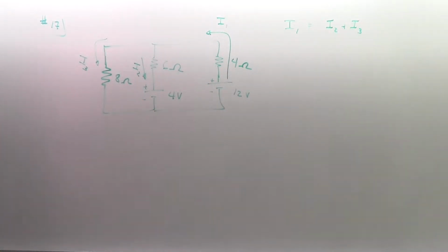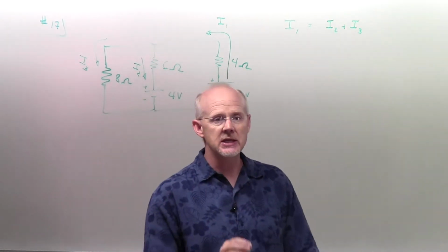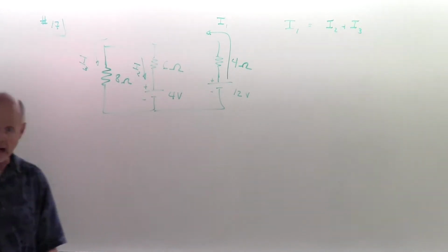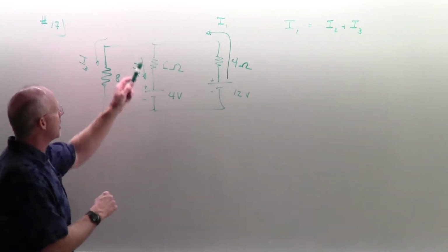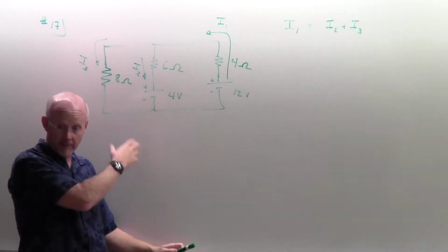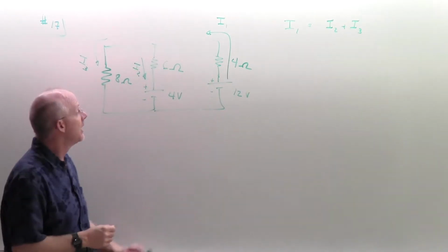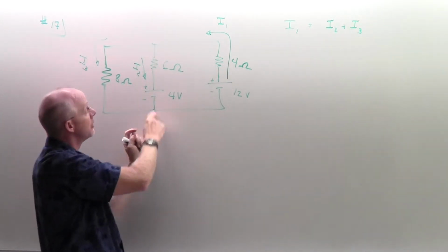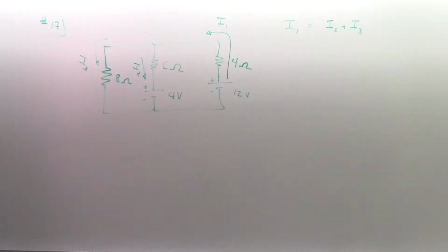And as I said last time, look at the little loops, because any other loop is a linear combination of the little loops. So you can see how many independent equations you get from the loops right away, and then you can go to your nodes and get the rest of them from the nodes. And so had I started there, I would have said, I'm going to get 2 equations from my loops. I need 3, so I must get 1 from the nodes. And you can see there's a node there. There's a node there too, but I'm thinking you can see how these two come together. This node is really the same as that node. It's not a new piece of information.